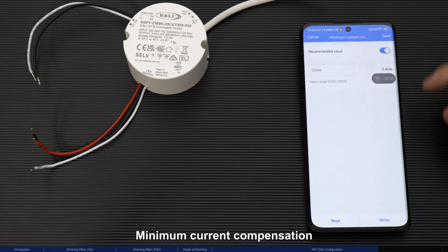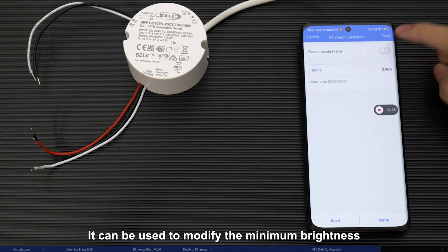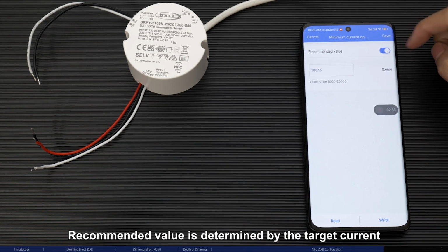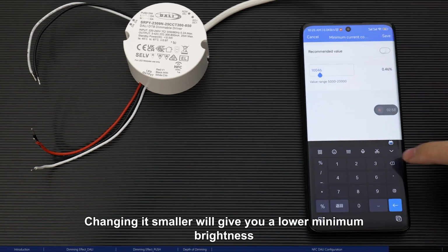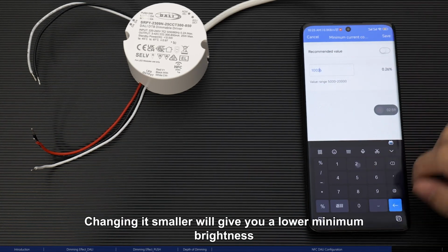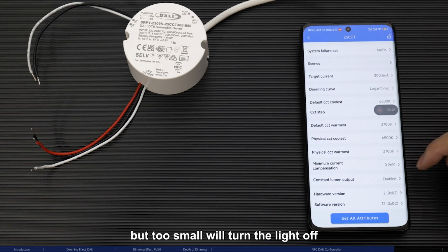Minimum current compensation, it can be used to modify the minimum brightness. The recommended value is determined by the target current. If it's not dark enough, then make it smaller. Changing it smaller will give you a lower minimum brightness, but too small will turn the light off.